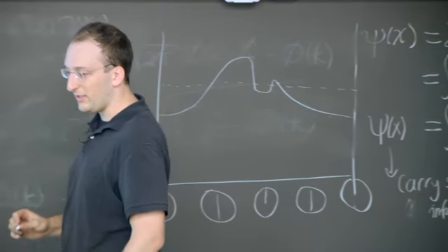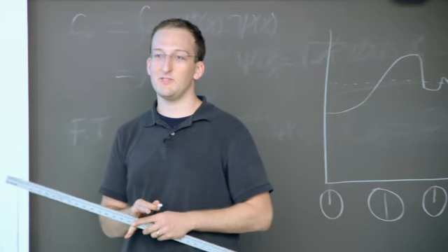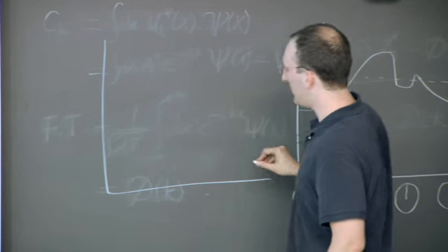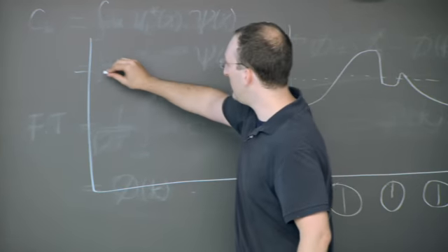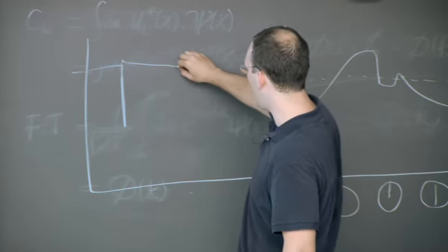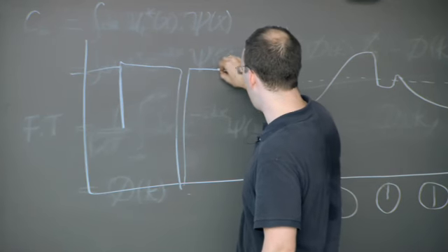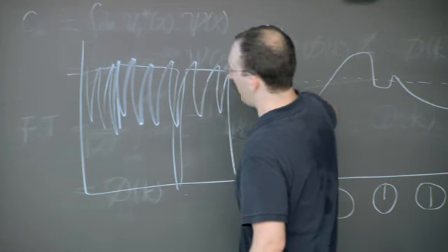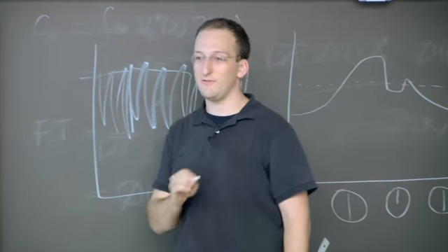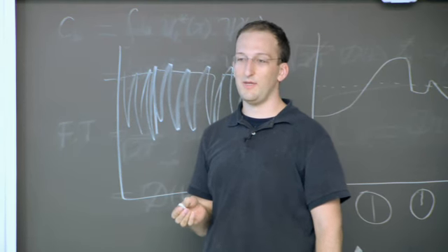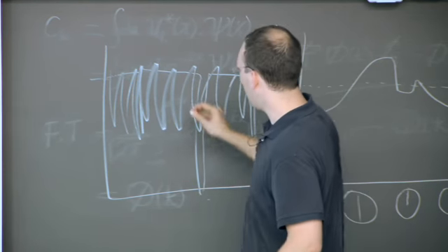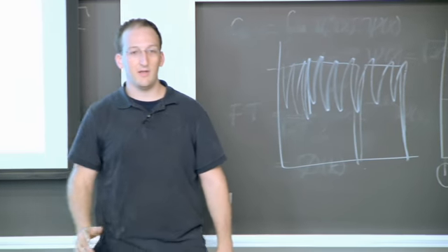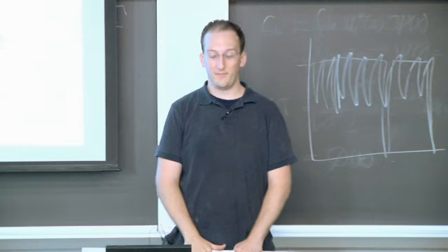I don't think too many plants in the US do it. I know the plants in France do, because I just saw a pretty cool graph of the power level versus fuel cycle. The US one looked something like this, where there was a partial shutdown, there was an unplanned outage, and then it went off. And the French one looked like this. So they try their best to follow the load demand. Now, having heat storage can help smooth out some of the shorter-term instabilities if you decide to design it right. And it's up to you to decide, do you want that or not?